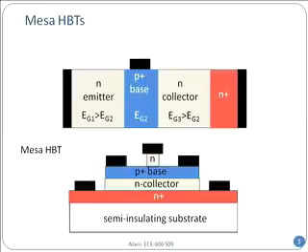You can see the N plus collector, the N plus sub-collector, which is the red, and the N collector, and the P plus base, and then N. You start with a larger device, and you sequentially etch to define these various regions.